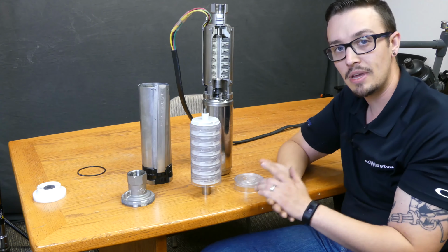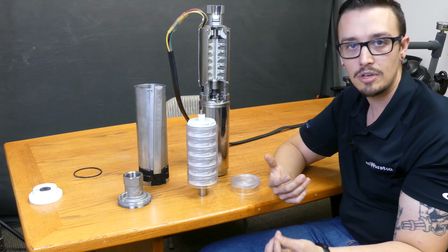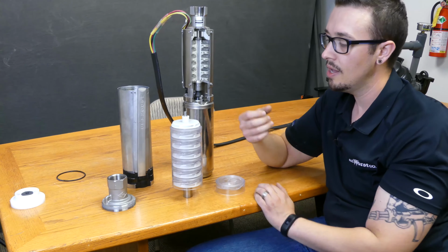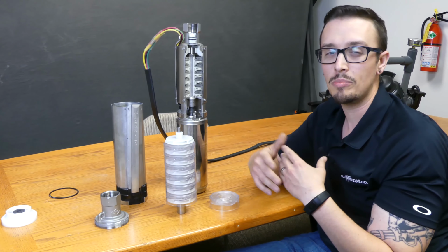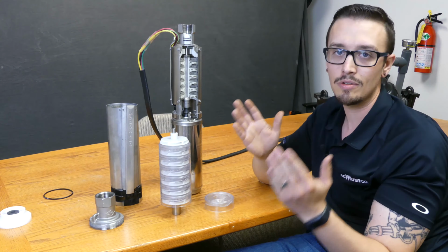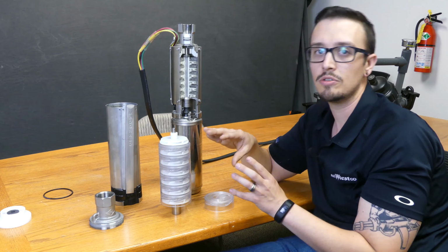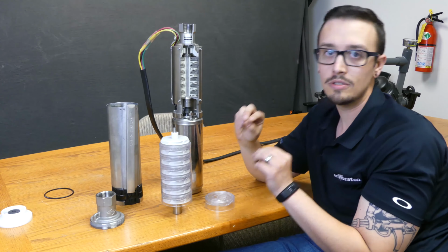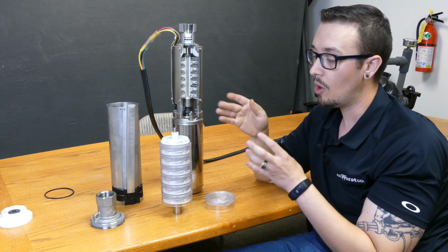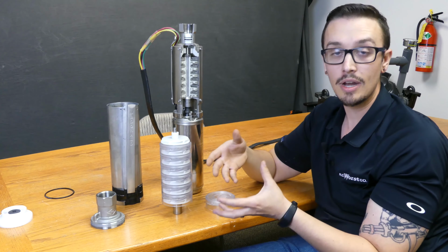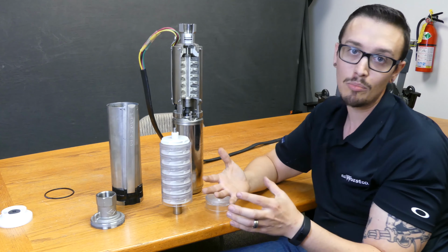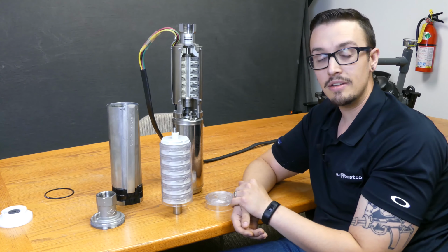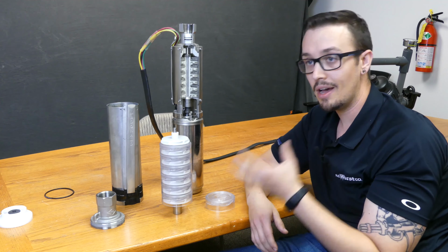I think there are some manufacturers out there, like with stainless steel pumps, where the impellers are fixed in place, and also with turbine pumps, where you can get away with a little bit more upthrust and downthrust and have a slightly wider range of operation. But in a residential setting, it's very easy to size the pump to where it's always going to operate efficiently and in its recommended operating range, because you don't generally need that broad range of operation.